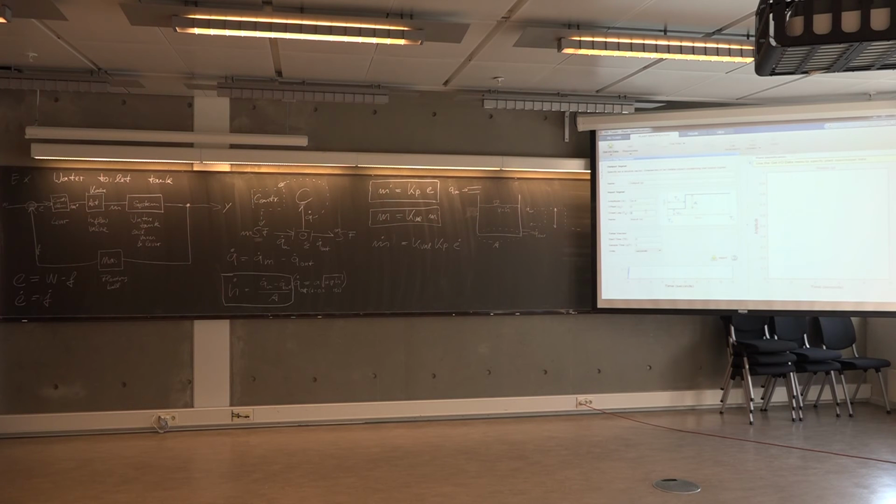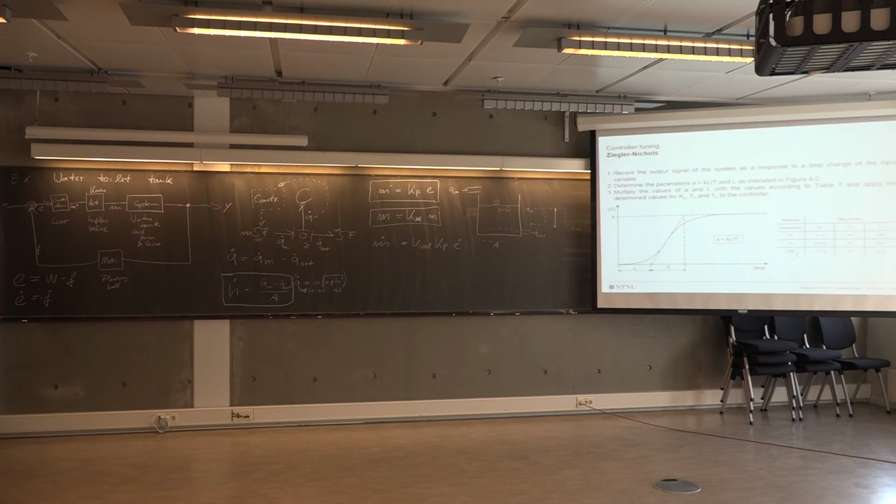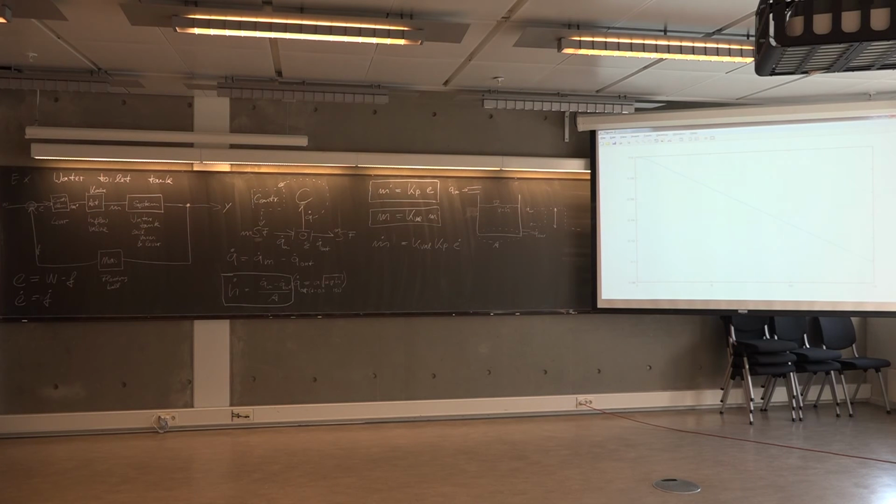And then this happens after 0.5 seconds. So that's how our imposed step looks like. And here, you need to specify the response, which should be in our workspace as y. The last equation I solved here was the system response, this one. And this should be now available to this tuning functionality.